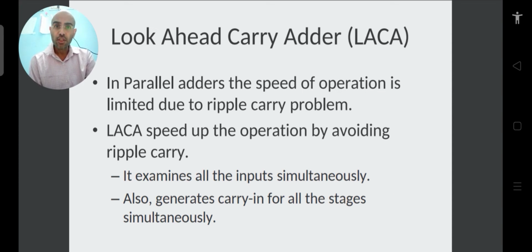So what was the logic to invent this? He invented it to overcome the shortcomings of the parallel adder. The parallel adder has the shortcoming that we have discussed, that the ripple carry is there and it takes more time to calculate the exact sum. Until the final carry output is generated, the propagation delay is more in the case of parallel adders.